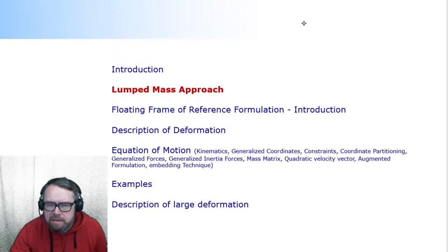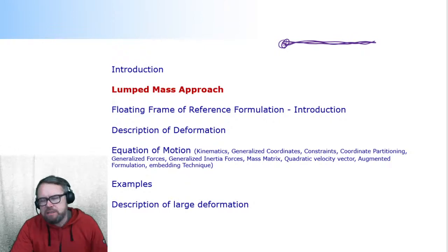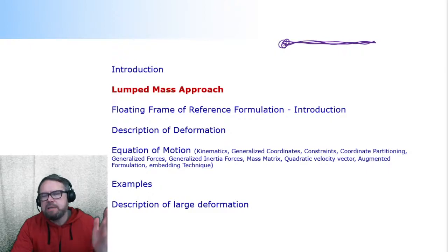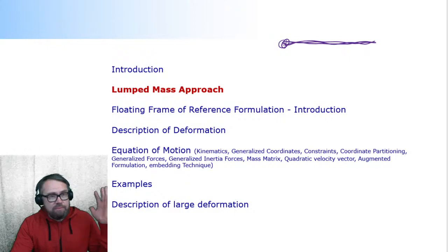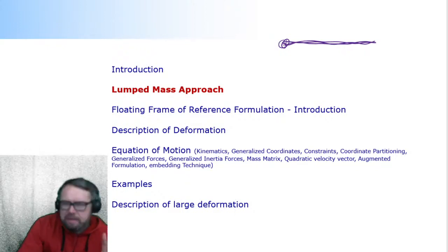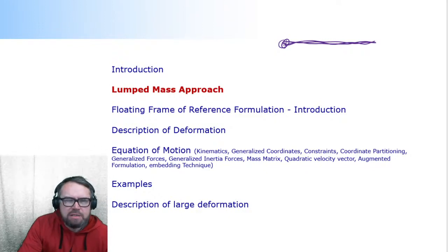It was an idea that, if you have, let's say, a pendulum like this, you first compute the pendulum behavior by assuming it to be rigid. Then afterwards, at each time step, you estimated how much the deformation was. And then you were superimposing the information concerning the flexibility and rigid body motion, and that was your final response. The problem was that the flexibility was detached from the overall motion. And this is not what you can see in real life. That's leading to poor responses.